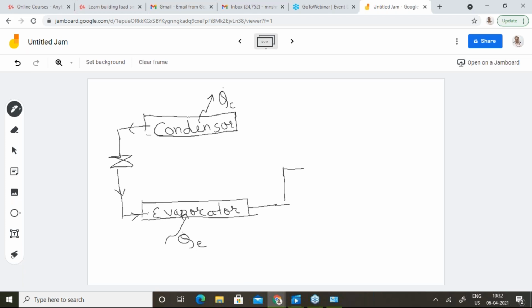So this is the conventional technology. Let us say this is your compressor. A refrigerant enters the compressor. We all know this at a lower pressure, and this compressor would take it to the higher pressure. So this compressor does a very important job of compressing the refrigerant from a low pressure, that is the suction pressure, to the discharge pressure.